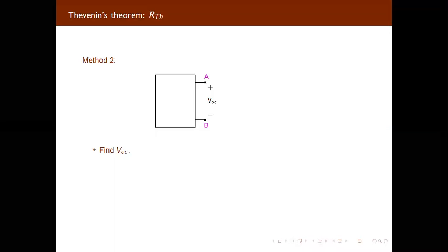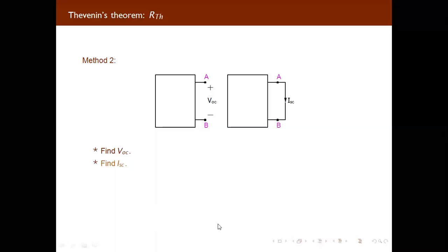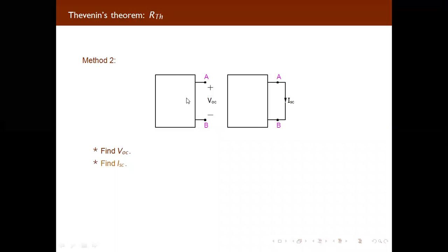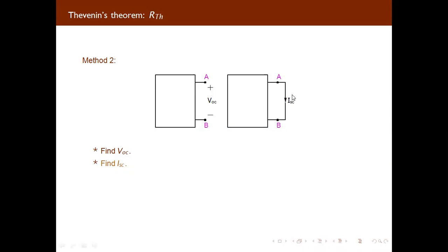If we are having any circuit, we can convert our Thevenin circuit into a Norton's. In the Thevenin circuit we are converting a complicated circuit into a simple circuit where we will get one voltage source that will be in series with the Thevenin equivalent resistance. In another language, we can convert that voltage source into a current source, and the value of resistance will remain the same, but it will be in parallel with this current source.